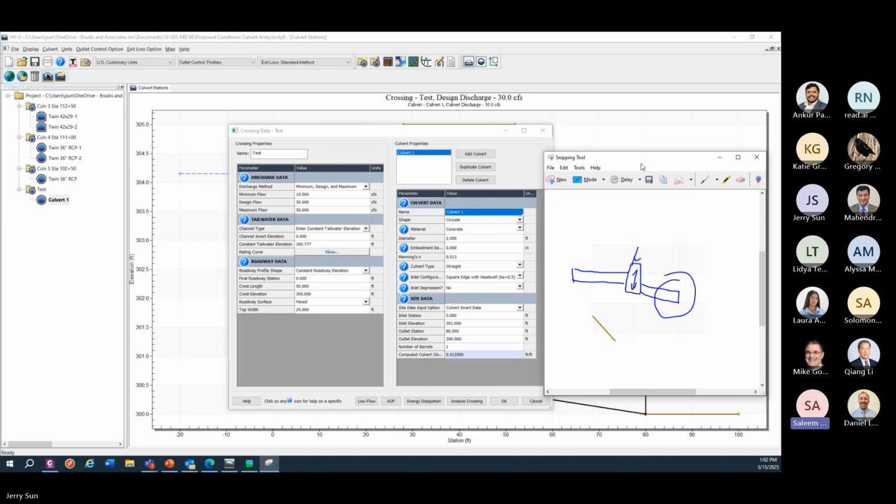If your culvert is discharging into a big pond, and the elevation of the pond may be a little higher than the invert of the downstream culvert, basically it can compute the size of the culvert, or the velocity, or how much flow is going to go. Right. Yeah, that's good information. The other information is for our engineers' purpose.